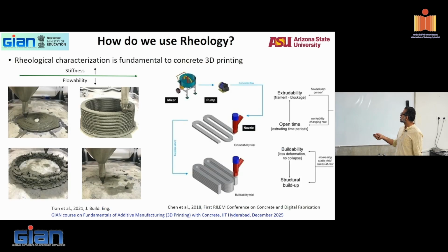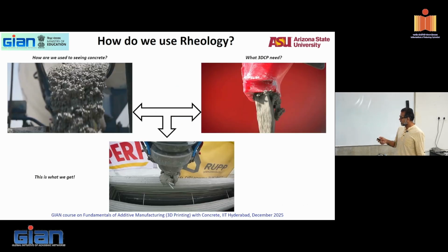I've showed you this picture. So extrudability, how much time period you can extrude, the open time, how much material will keep the yield stress and plastic viscosity for it to be extruded out, and then how well you can build up and the structural buildup. So here are some videos that, let me see if we can show you those videos.